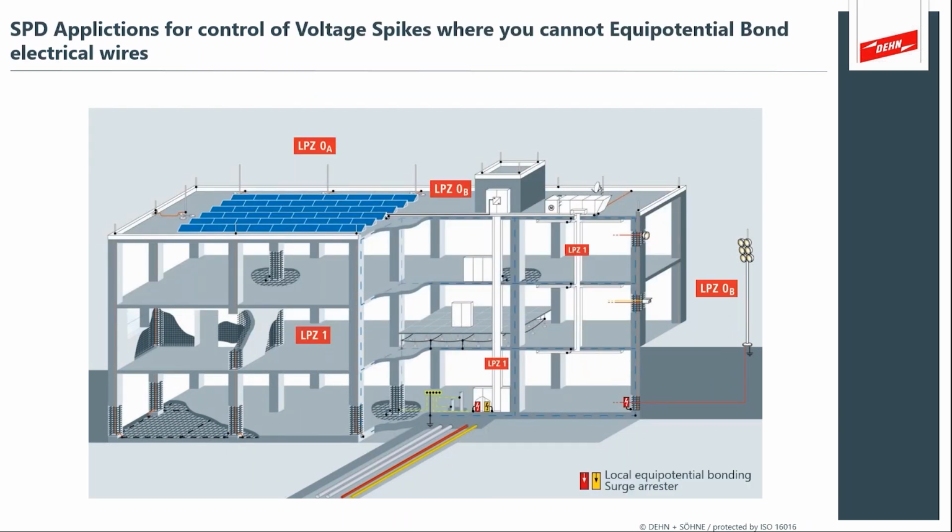And then we talk about electrical bonding. Now, of course, you can't take your incoming AC power and bond it to your earthing system. That's what electrical power is doing. You're not bonding it. So that's what the surge protection device serves. The surge protection device, the SPD, serves as that momentary bond to control that side flash voltage so that it doesn't puncture into your conductors or blow out your data control system or your sensitive radio on the top of your antenna system or your security camera systems that are mounted around the side of the structure.